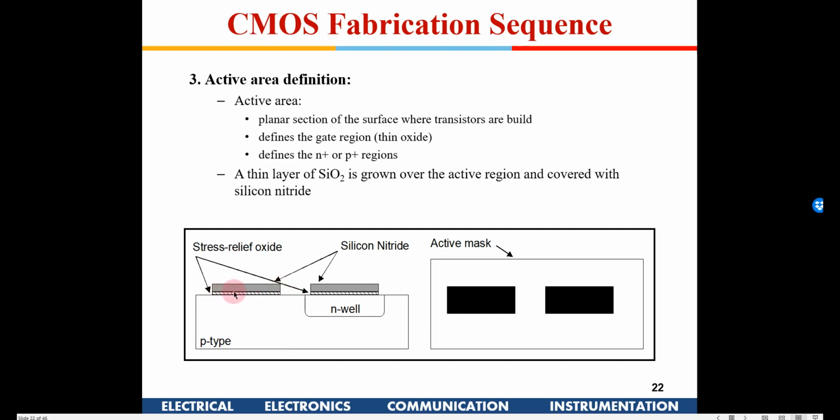Again we put an oxide here, and on top of that photoresist or silicon nitride. Now if you see here, oxidation happens in many steps. In these steps you can use wet oxidation, because finally these are going to be removed. So now you have put an oxidation, and a photoresist on top of that, and removed the photoresist where we are going to pump in P plus rings across this.